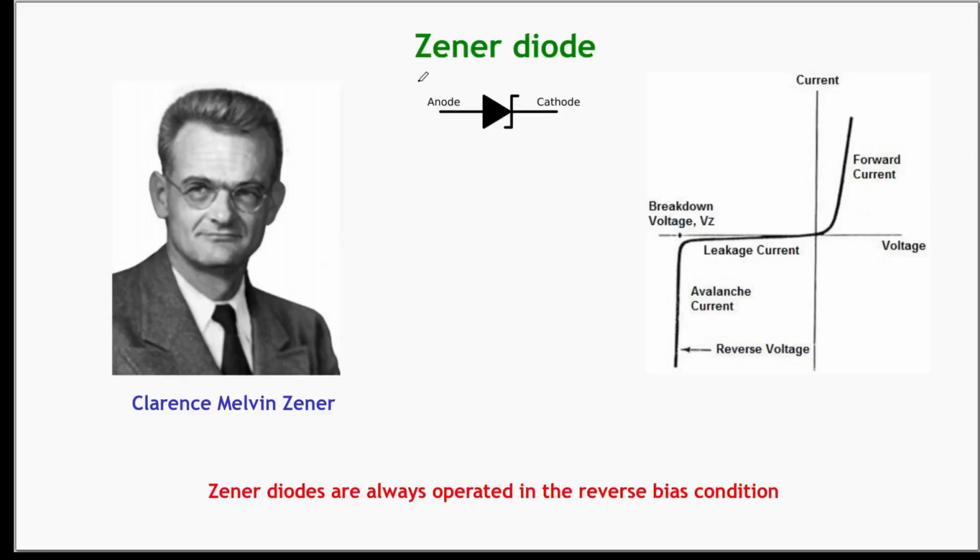Hello, welcome back. In this video, we'll discuss the Zener diode. In the case of a PN junction diode, while it is reverse biased, at a particular voltage called the breakdown voltage, suddenly a large reverse current starts flowing in the circuit. We have said that it is due to the breakdown of the diode, and under the breakdown conditions, the covalent bonds will be broken.